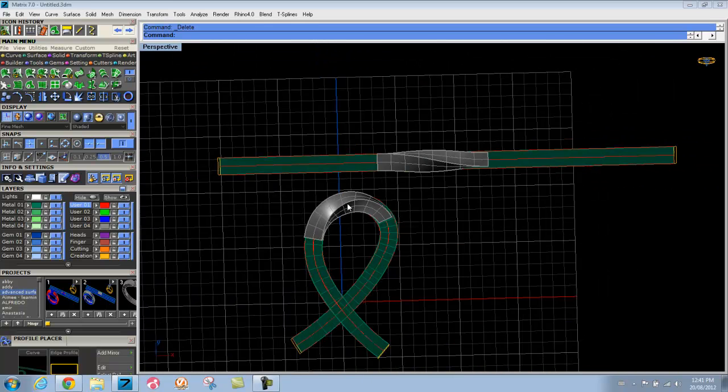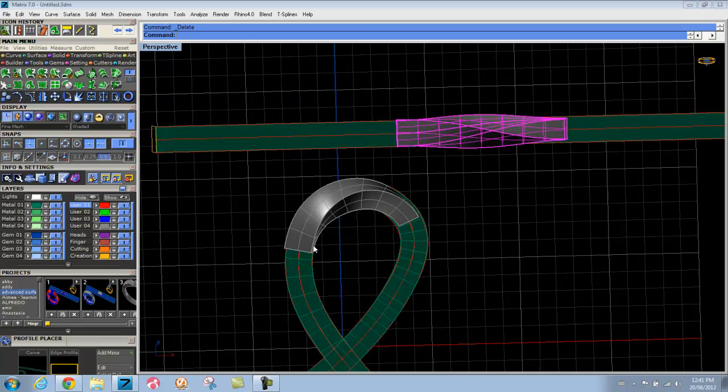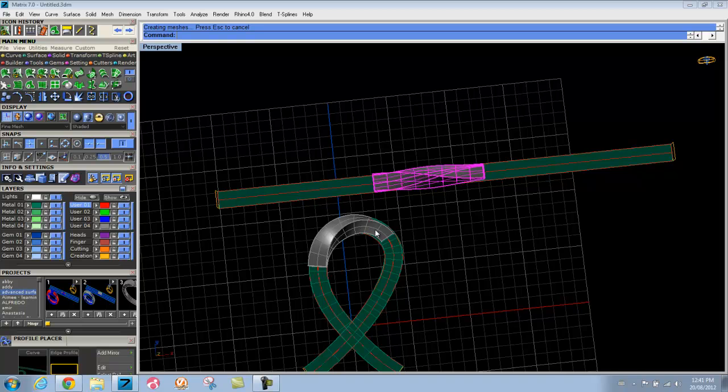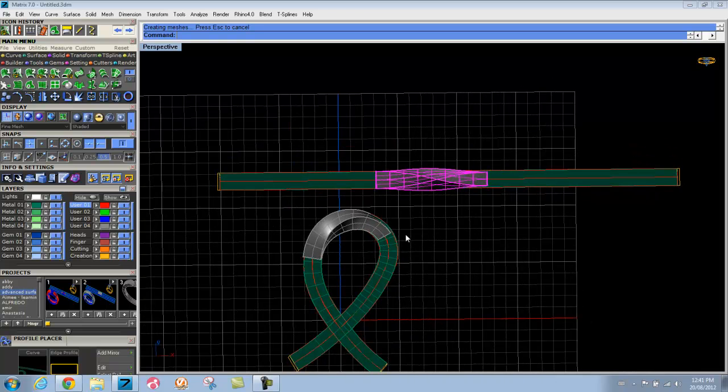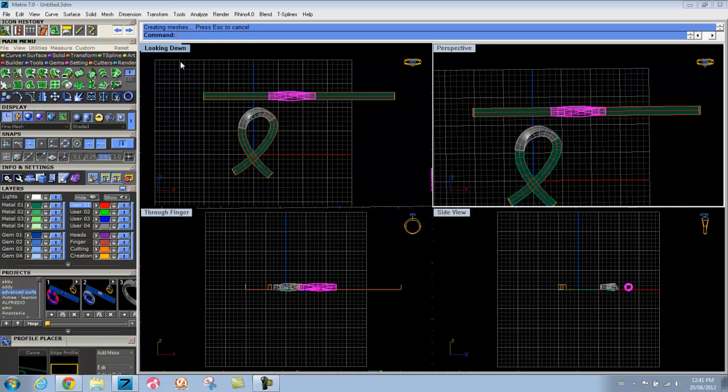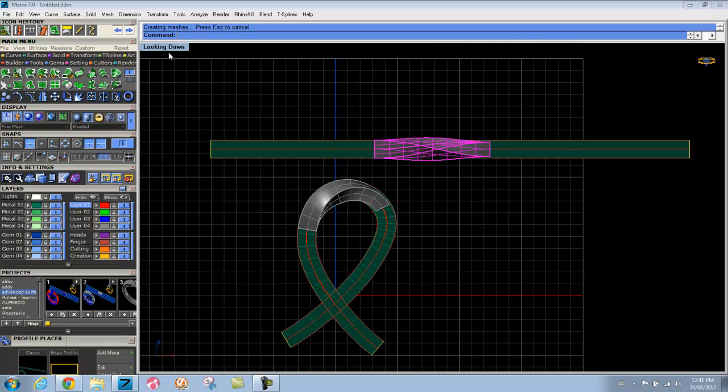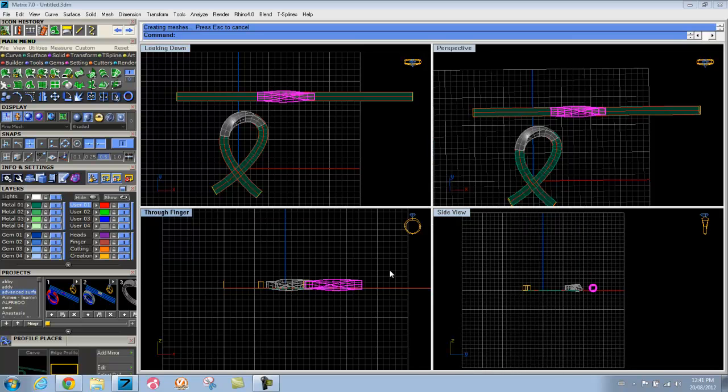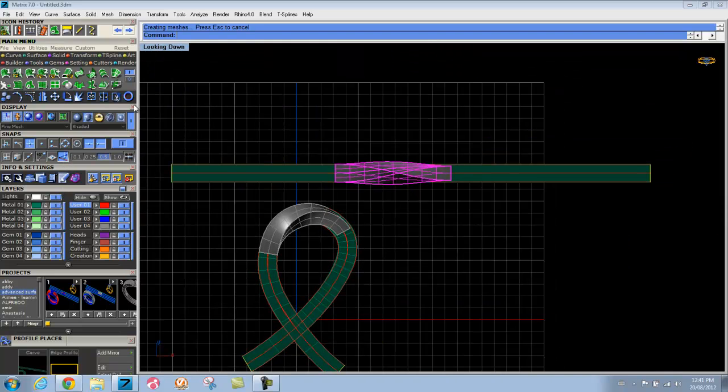So now to adjust the length of this section, I just have to do a 1D scale to stretch this out, because I want this to begin here, about right there. It looks good, but I want this to continue further on, maybe around here. To make sure that I don't distort the shape, if I do a 1D scale to pull it up in the Z-axis slightly, I might turn on project just to make sure that this is going to stay flat. And I'll do a 1D scale from here, hold on to Shift, so I can just adjust the way that that looks as well.